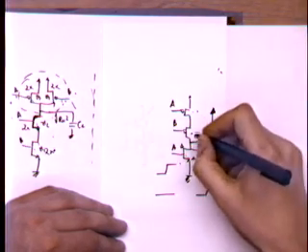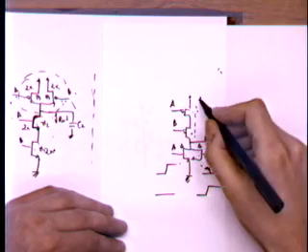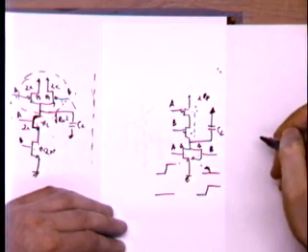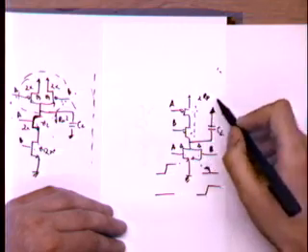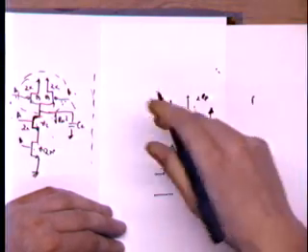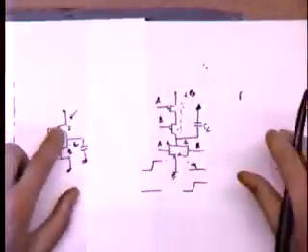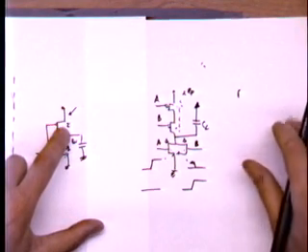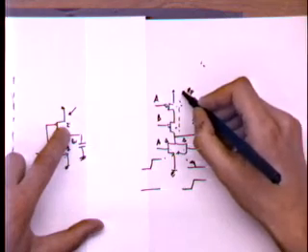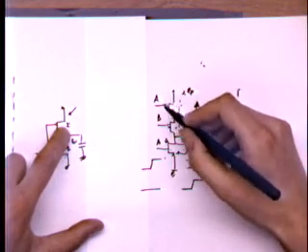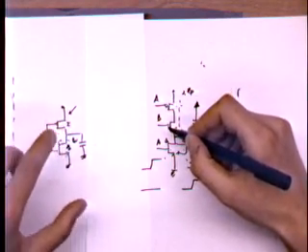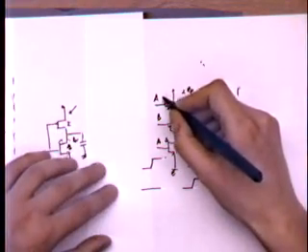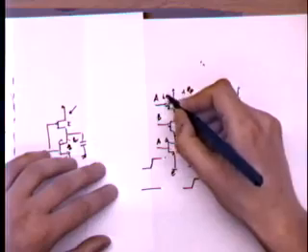In this case, the pull-up strength is given by 2 RP, and we want 2 RP to be equal to the pull-up resistance of our equivalent inverter, which was for a 2x size inverter. Therefore, we need to make each of these devices twice as wide as it was in the inverter case, so each of these devices ends up being twice times 2, so 4x.